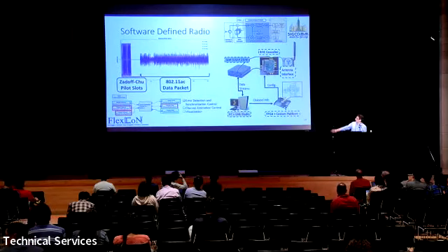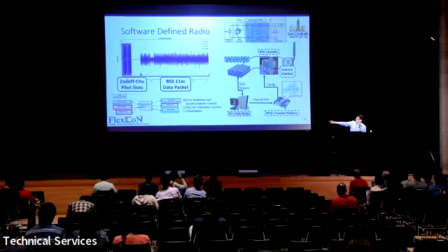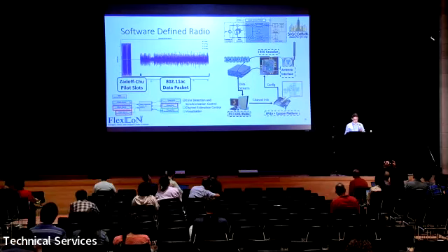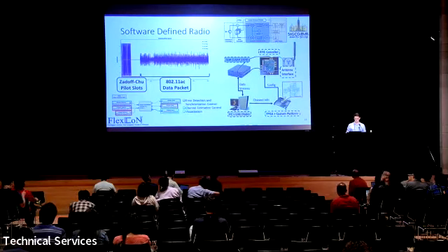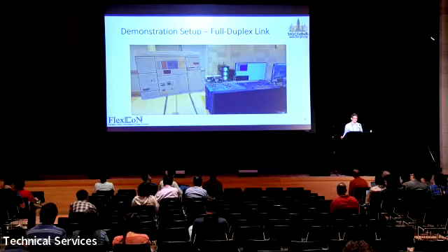The communication is all handled by the software-defined radio and the associated flow graph that we built with it. We developed a packet structure that is based on the 802.11ac data packet format. We designed pilot symbols in order to maximize our self-interference channel measurements. And we developed a controller that makes sure that the whole system is in the loop, taking care of the FPGA communications, the canceller configuration, and the transmit and receive streams. Now, at the demo, we showed you a two-radio setup, two full duplex radios, and a working link between them. But for the purposes of this presentation, we're going to go through the operation of one of them.